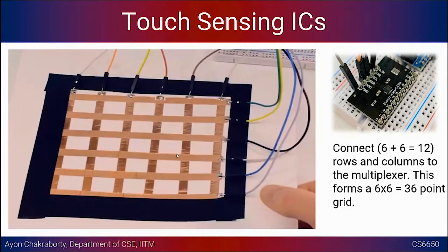Okay, and you can do something of this sort also, right. If you have this 12 channel capacitive sensor, you can form a grid like this, so that you have 6 in one direction and 6 in the other direction, and whenever you touch one of these areas, both this and this will become activated to some extent, and you need to figure out some metric to figure that out, right. You have to figure out, of all these 36 points in the grid, which particular point was touched. There are standard algorithms to do this, but you can also figure out your own.